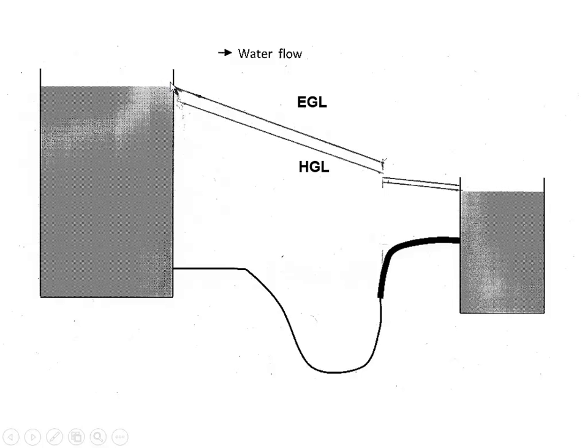And then it's kind of hard to draw this because what you've got to draw is two different slopes, but the HGL needs to finish at the water surface. And so in a way, it's kind of an iterative thing where you need to draw a shallower slope for this second segment because the pipe diameter is larger.